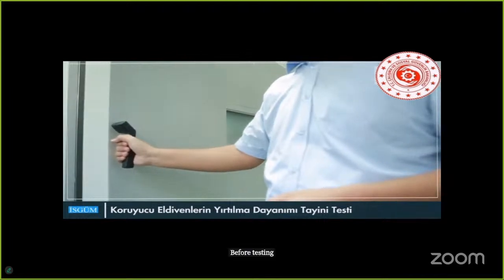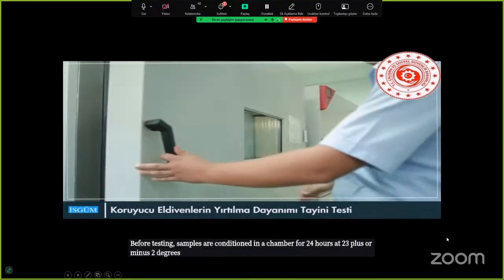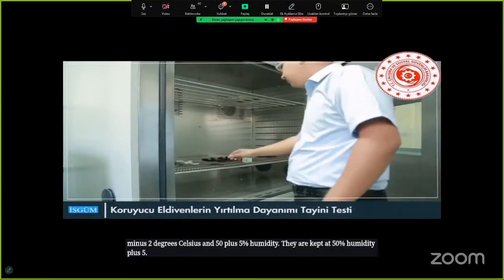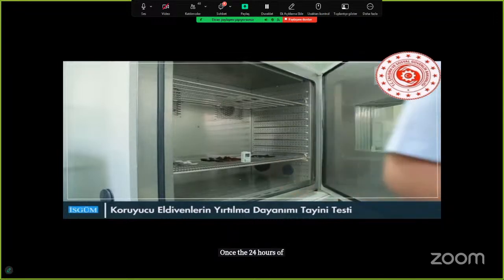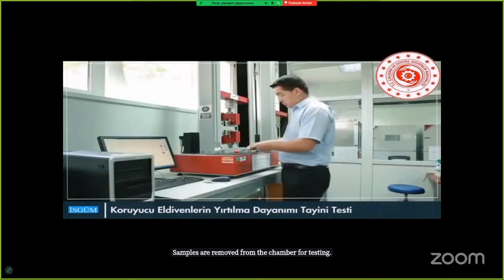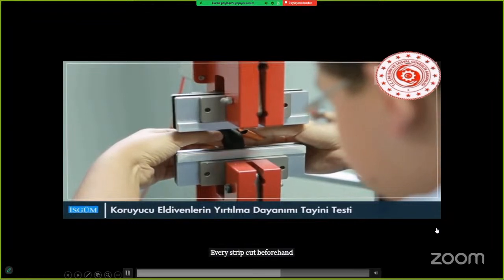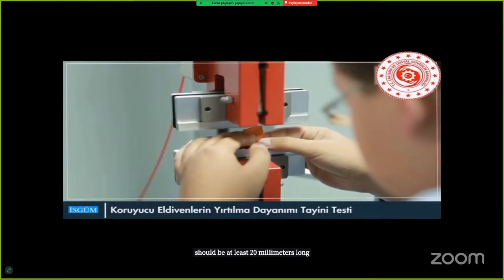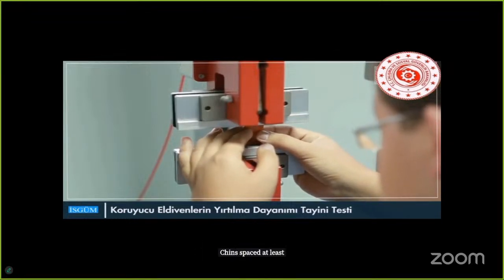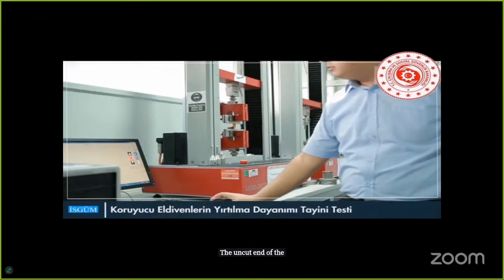Before testing, samples are conditioned in a chamber for 24 hours at 23 plus or minus 2 degrees Celsius and 50 plus or minus 5% humidity. Once the 24 hours of conditioning are complete, samples are removed from the chamber for testing. Every strip cut beforehand should be at least 20 millimeters long, aligned with the sample's length. Jaws spaced at least 10 millimeters apart are clamped to the stretching test apparatus. The uncut end of the test sample is released.